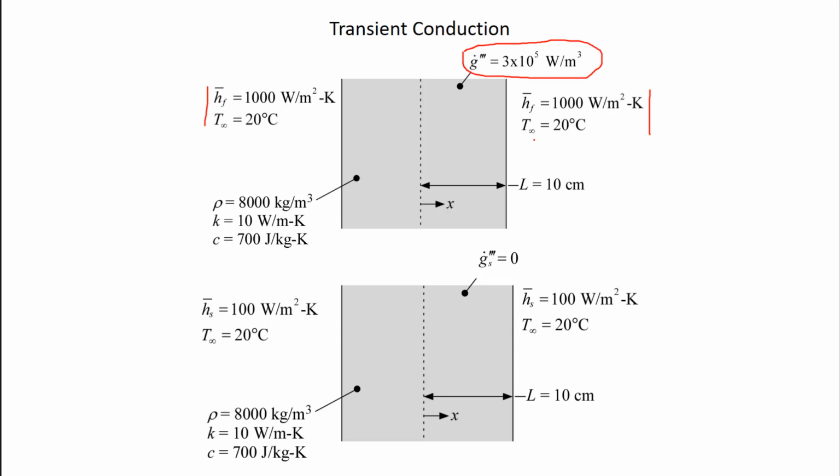So it runs like that for a very long time, comes to some steady state temperature distribution in this kind of on state, and at some time the current lead is shut off, and what that does is actually two things. It shuts off the current, so the ohmic generation drops to zero, but it also shuts off the cooling, so the heat transfer coefficient drops by an order of magnitude. So both those two things happen at time equals zero, and we're interested in looking at the deactivation process.